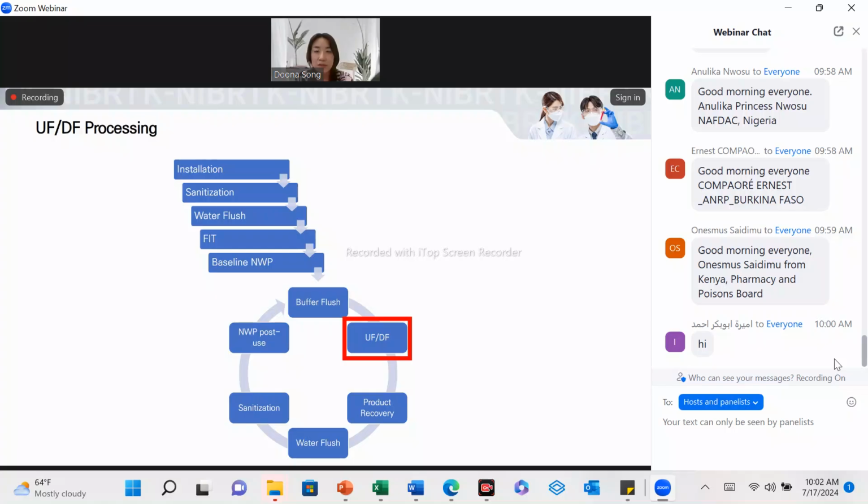For the ultrafiltration step, the product is concentrated to the target concentration. During the filtration process, unlike NFF, it is less prone to clogging or fouling. Once the target protein concentration is reached, the diafiltration process can begin. While the protein solution is recirculating, a new buffer solution is added to the feed. As the diafiltration proceeds, the new buffer solution feed replaces the original buffer.